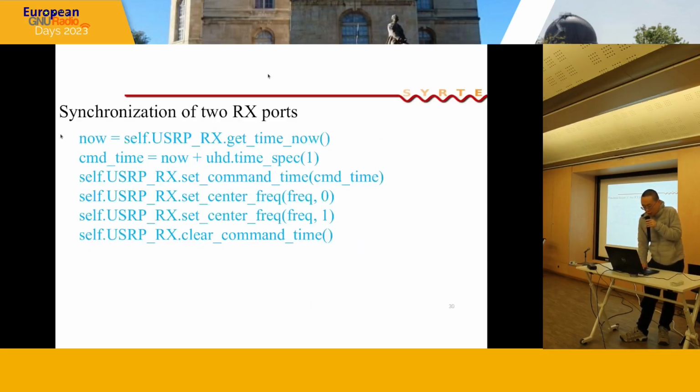And for the reproducibility of our experiment, we need to synchronize the two RX ports through this piece of code. As you can see, the set command time ensures that the two RX frequencies and phases are synchronized. They happen at the same time.